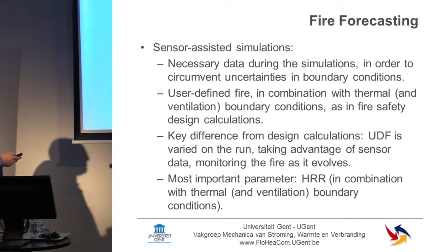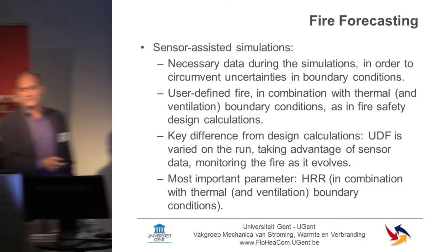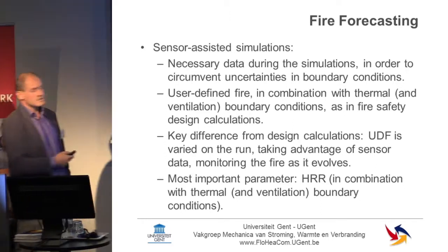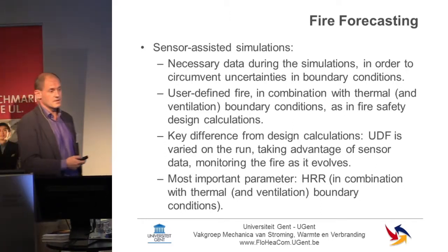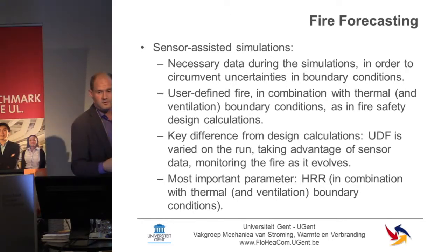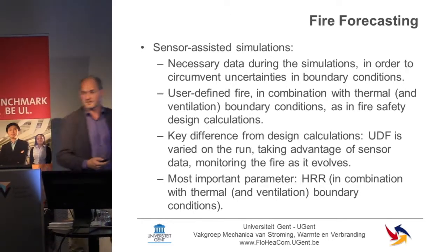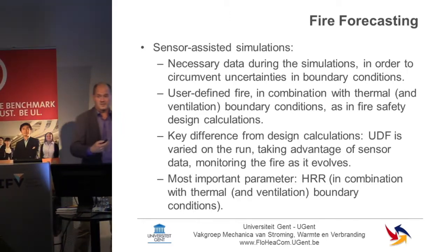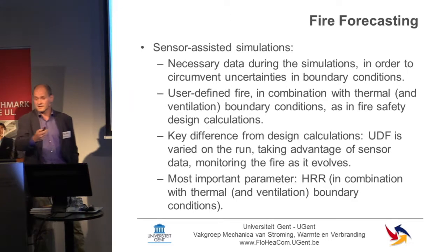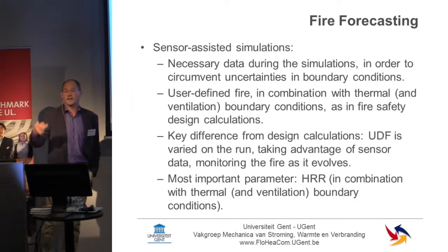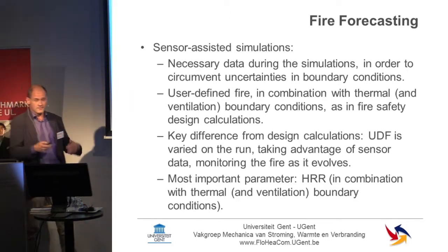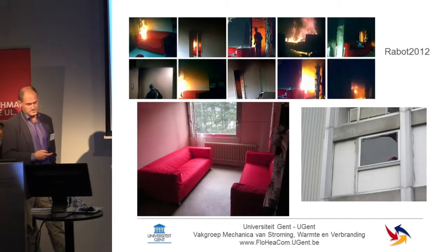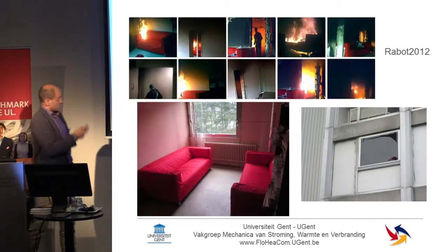So we feel that the most important parameter that we need is the heat release rate in combination with the thermal parameters, how much heat is leaving the location, and ventilation parameters. Are the doors open, closed? Is someone opening a door? Is there a window open? And you can introduce that in the zone modeling.